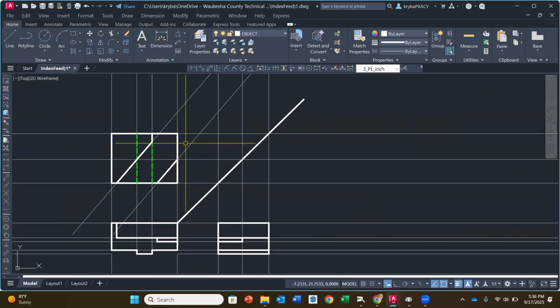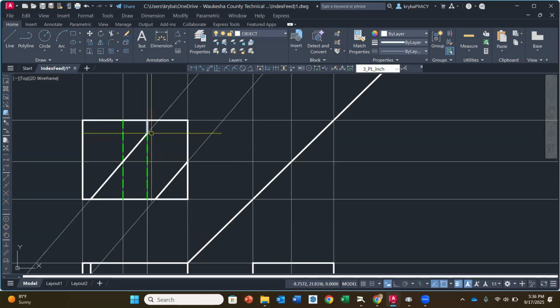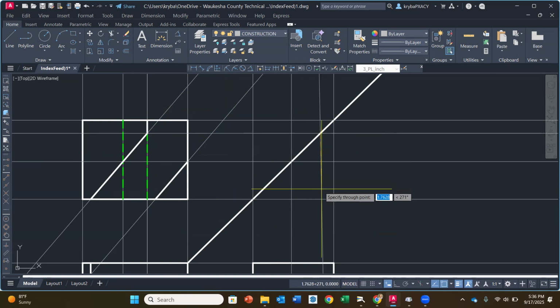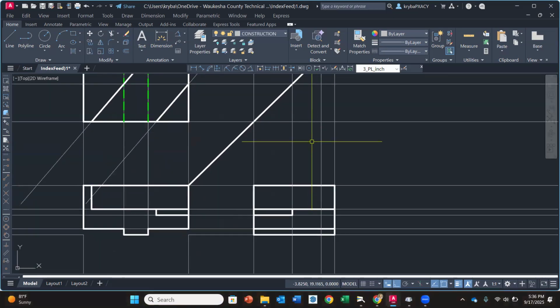We are going to push that over to our right side view. So we're going to take this corner right here and we're going to go horizontal construction line and down into our right side view. So go back to the construction line layer, construction line, grab that corner, make a horizontal line through, repeat, and then we're going to take that intersection and go straight down. I need my ortho on. There we go. Okay. And then now what this tells us is where that came over.